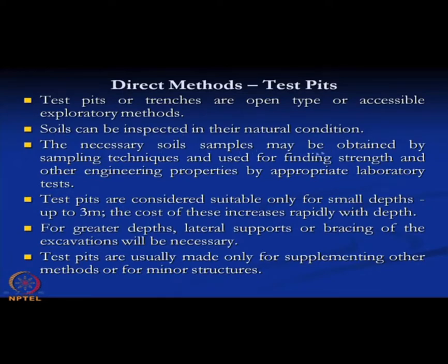The necessary soil sample may be obtained by sampling techniques and used for finding strength and other engineering properties by appropriate laboratory tests. Test pits are considered suitable only for small depths, up to 3 meters, and their cost increases rapidly with depth. So this direct method by test pits or trenches is suitable for a very small depth up to 3 meters, because we have to construct the trench down to the level where we place the foundation. Now, for greater depth, lateral support or bracing of the excavation will be necessary.